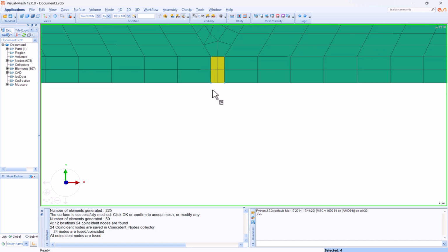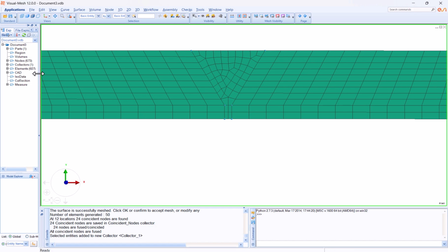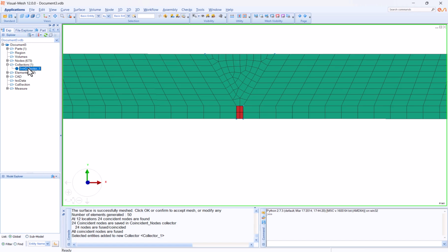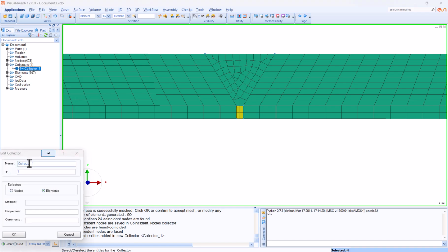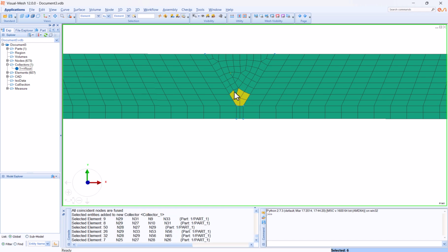This is going to be my root pass. So by right click and from tools, add to new collector, and I have to rename this collector. So from edit, we say this one is root pass. Okay, we click somewhere on the screen. Now we carefully selecting this one.